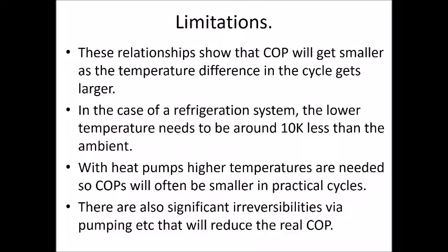As the temperature difference gets larger, so look at your equation that showed the temperature form of the COP, as the temperature difference gets larger, the COP gets lower. Now that's obviously the opposite to what we learnt in power cycles. To maximize our efficiency, we maximize the temperature difference.